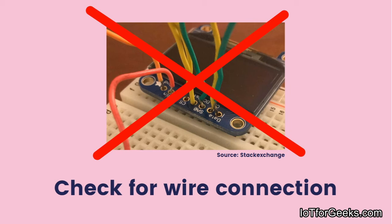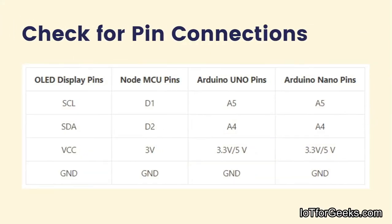I'll suggest you either use a breadboard or just directly solder the wires. If you're sure that all the connections are good, then go for the next check, and that is the pin connection. Check the proper pinout. If you have wrong connections, then the display will not even start. So please follow the pin connection as given below. There is a pin connection for NodeMCU, Arduino Uno and Arduino Nano. You can pause this video and see it for the respective boards.